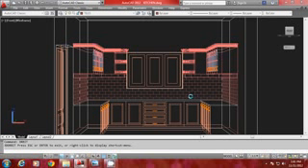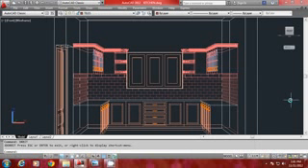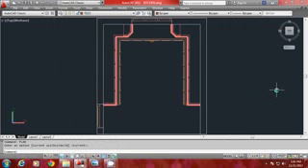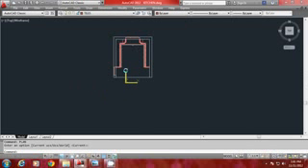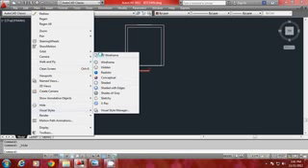So this is the simplest and the easiest method, but we have some limitations in this method. So here we can't control certain parameters like the position of the camera, the focal length of the camera, and the type of perspective, etc. So this is where we have to make use of a very useful and versatile command in Autocad, and this command is called dynamic viewing or dview. So just go to the dview command. You have to give the dview command in Autocad.